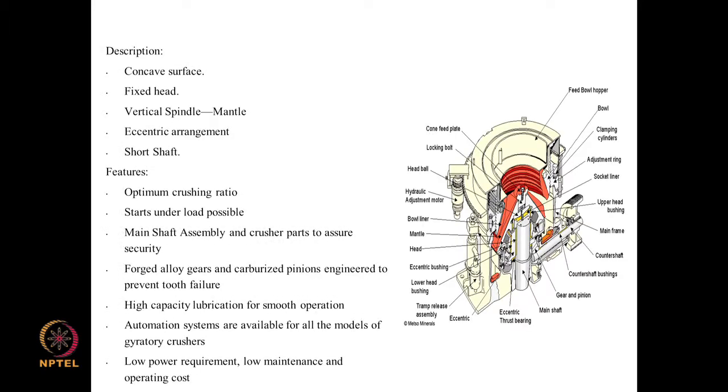And this is what a gyratory crusher looks like. Again, pretty large equipment, lot of moving parts. One thing about use of crushers in industry, they do lead to a lot of downtime, because you are trying to crush very large particles, very hot particles. Frequently there are problems like damage to the surfaces that are coming in contact with the particles, and there are also stoppages due to plugging of the pathways and so on. So, crushers are high maintenance equipment.